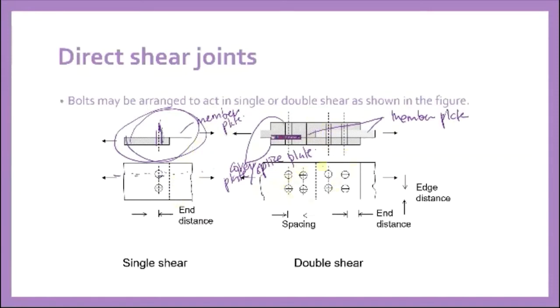This is similar. This is the plan view and this one is the cross section view. For example, you cut it here. From the front you will see this. So you see it like this. This is the hole. Spacing is from the centroid of one bolt to the centroid of the bolt next to it. And the distance from the centroid of the outermost bolt to the end is the edge distance, from the centroid to the end here. This is edge distance and this is spacing.